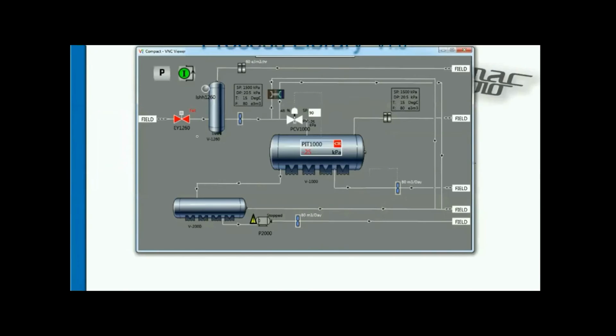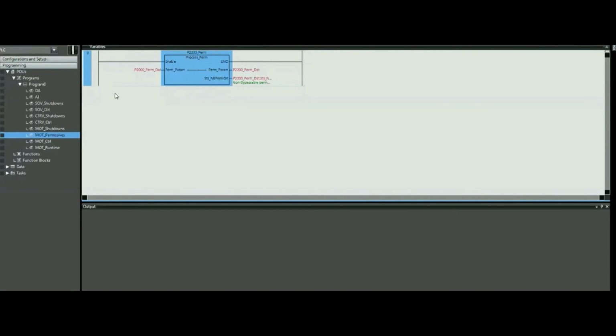So hopefully that gives you guys an idea on how to utilize this object. Say, for example, we're going to add now some permissive for a standalone piece of equipment. We're going to discover here in a moment what it takes to do that so we can have it added to our system. First thing we would like to do is create another permissives block, add some permissives and configure our block so we can use it with our HMI. So let's go ahead and do that.